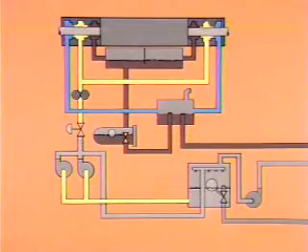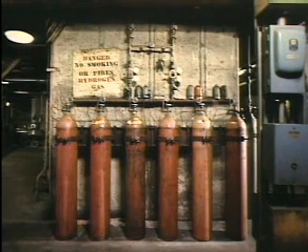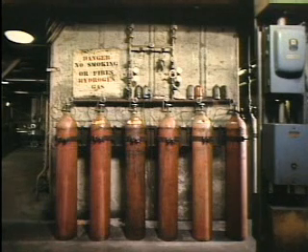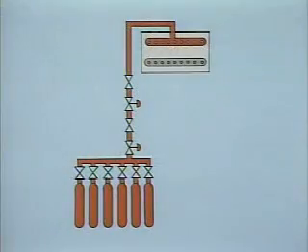The plant operator can adjust the control valve in the seal oil supply line so that the proper pressure is maintained. To maintain the required concentration of hydrogen in a generator cooling system, hydrogen has to be added to the system from time to time. The hydrogen may also have to be replaced entirely after maintenance work is performed on the generator.